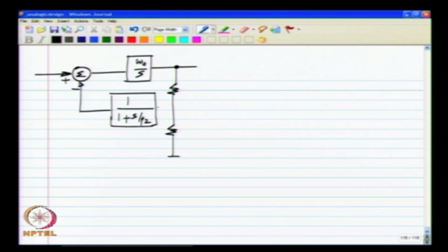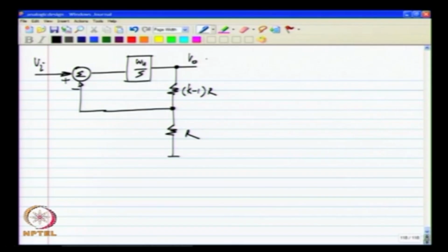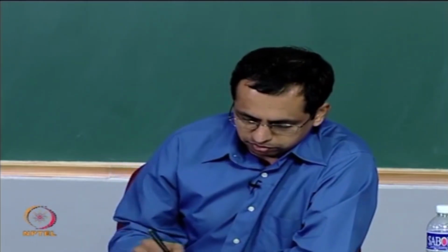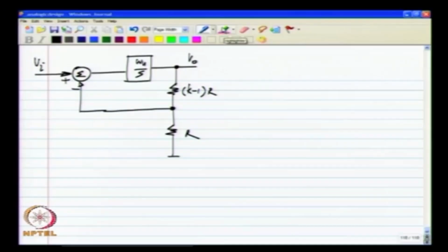And I will take initially, let me take simply the ideal case with no extra parasitic poles. And we already know that this is unconditionally stable and there is no ringing, and we will see what it corresponds to in the Nyquist plot. What is the loop gain in this case? If I break the system here, make input equal to 0, I will easily evaluate the loop gain to be omega u divided by k s.